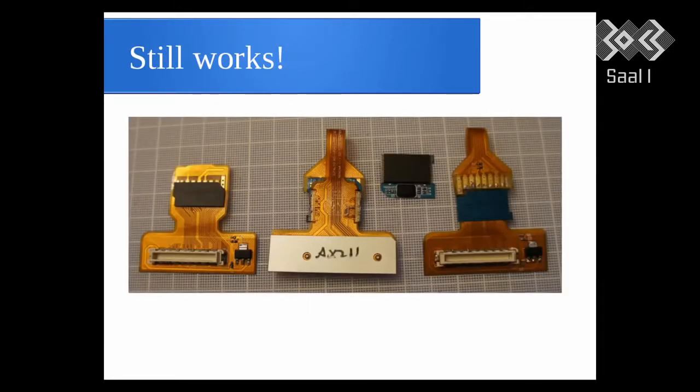Now, there's something interesting. Bunny showed this picture earlier, which shows the AX211, nicely labeled, right in the middle, with no NAND attached anymore. The idea was you're supposed to use the ROMulator that we wrote to emulate the ROM. But the interesting thing is, with this particular card, if you reset it, set it to command 0, it'll still respond to some commands. It'll respond to command 0, because that means go ready. It will respond to things like turn CRC on or off. But the go ready command, the hey, I want to actually read the file system command, doesn't work, because of course it doesn't have either firmware or any NAND flash to store it on.